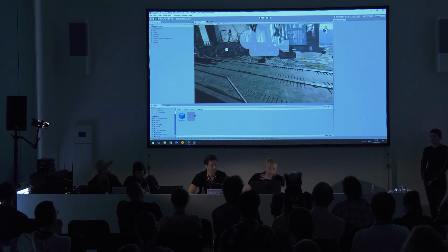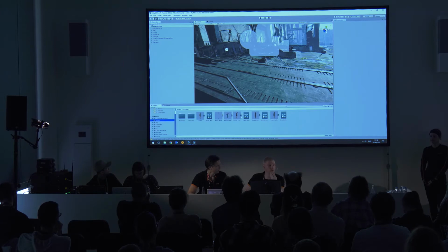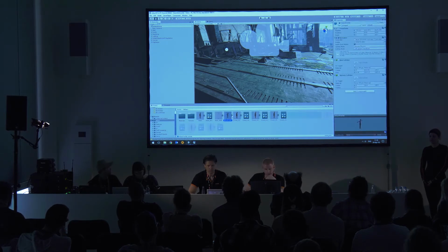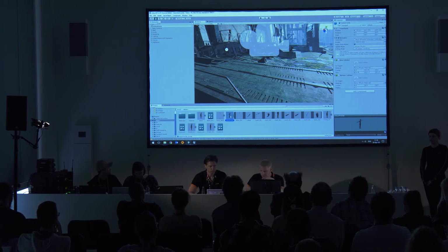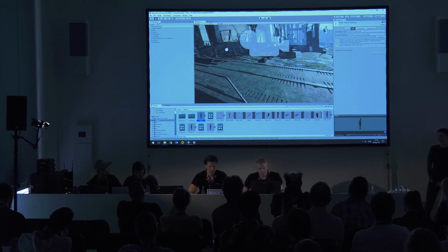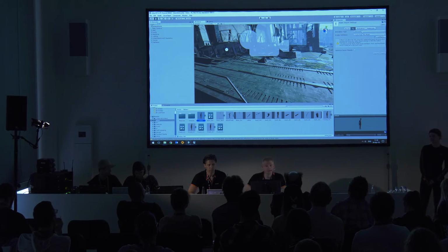To show you how easy it is, I just took the default Adam character. The only thing I've actually changed is that it's in a T-pose instead of a neutral pose, because we do assume that the first pose is T-pose in Unity. What we always need to check with the rig is that it's, first of all, set to humanoid.